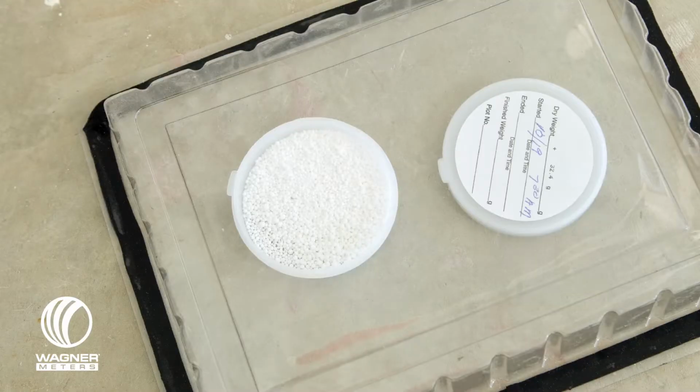To help ensure a successful installation outcome, we recommend you perform accurate concrete moisture testing on the slab before laying any flooring. Prevention is way cheaper in dollars, time, and reputation. And believe me, I'm not talking about doing calcium chloride testing. I'm talking about the in situ relative humidity test method that's ASTM F2170 compliant. This is the only test that will give you an accurate reading for future moisture in the slab.